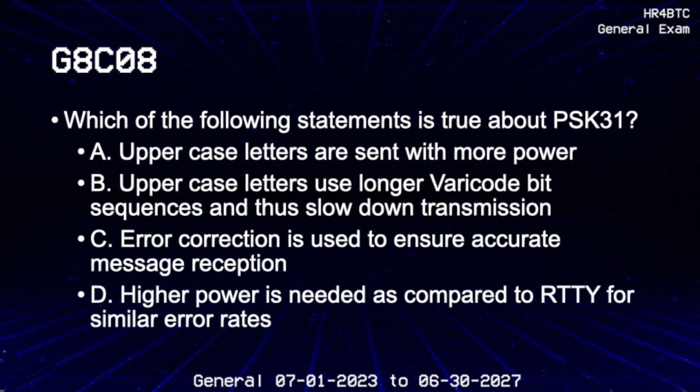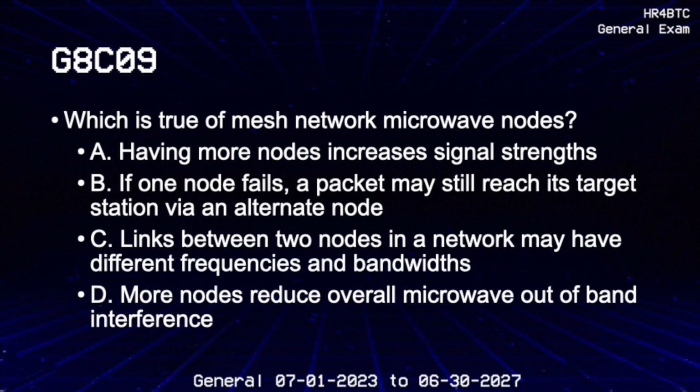Which of the following statements is true about PSK31? Uppercase letters use longer varicode bit sequences and thus slow down transmission. Which is true of mesh network microwave nodes? If one node fails, a packet may still reach its target station via an alternate node.